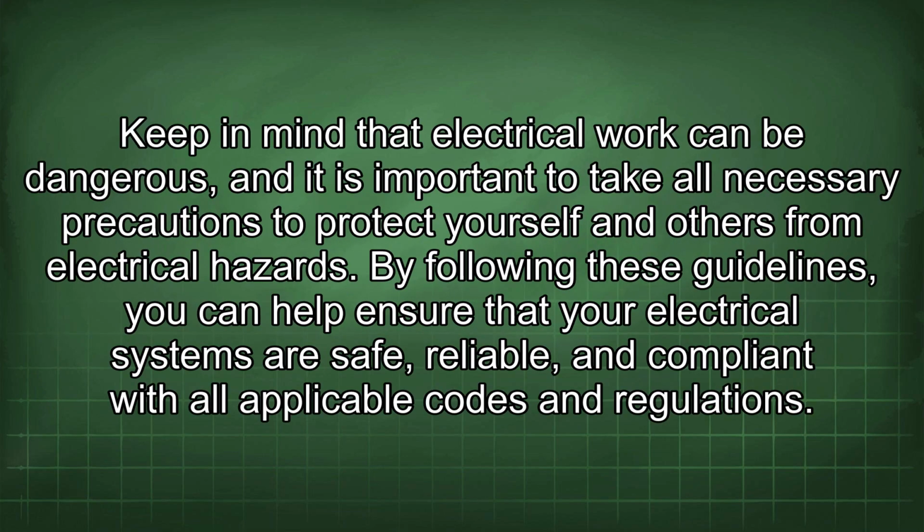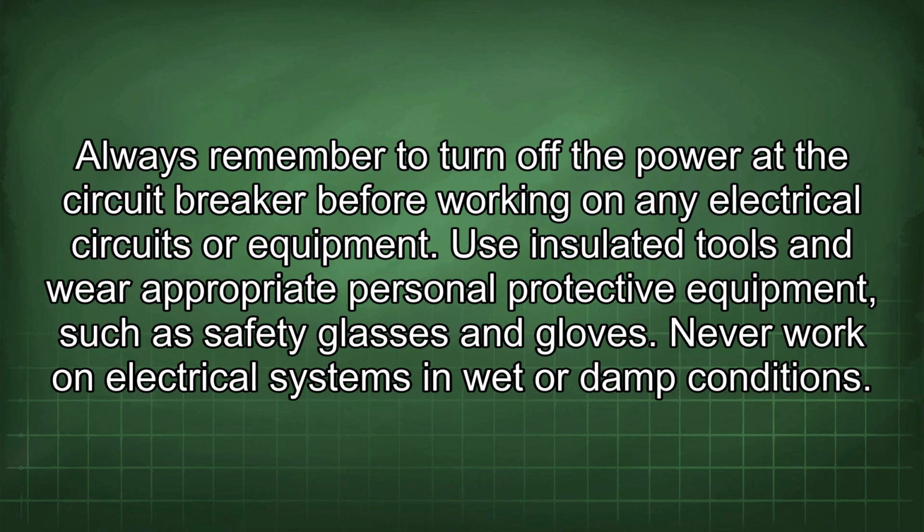Keep in mind that electrical work can be dangerous, and it is important to take all necessary precautions to protect yourself and others from electrical hazards. By following these guidelines, you can help ensure that your electrical systems are safe, reliable, and compliant with all applicable codes and regulations. Always remember to turn off the power at the circuit breaker before working on any electrical circuits or equipment. Use insulated tools and wear appropriate personal protective equipment such as safety glasses and gloves. Never work on electrical systems in wet or damp conditions.